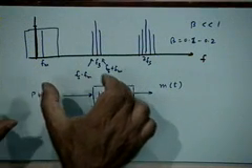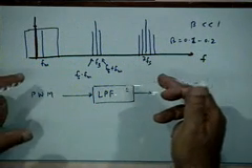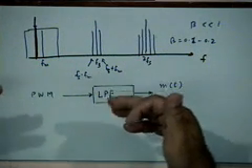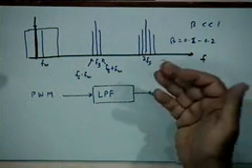So basically, we are saying that our information rate is much smaller than the bandwidth available to us. It's only that it's convenient to work with time division multiplexing rather than frequency division multiplexing. So bandwidth becomes a secondary issue in this particular situation. Really speaking, the bandwidth is not secondary, because ultimately in a certain bandwidth you have to transmit a given number of messages.